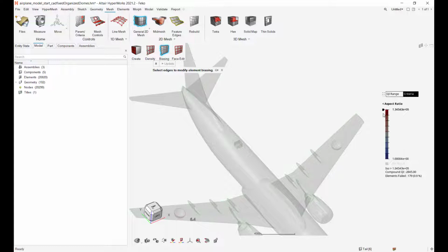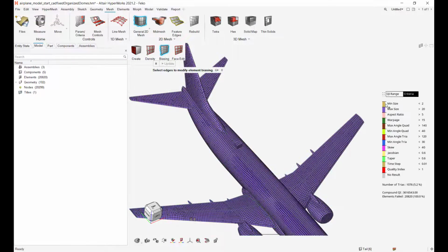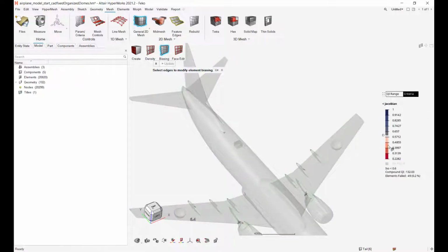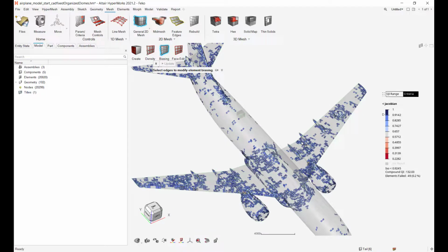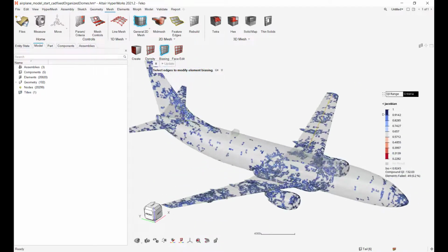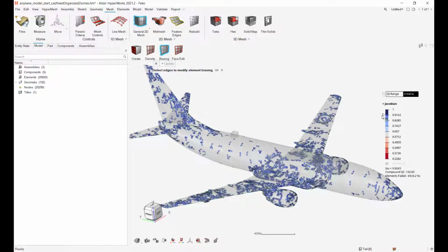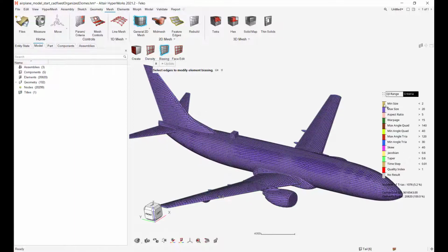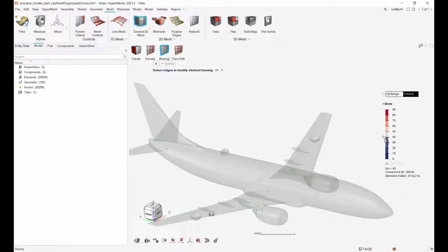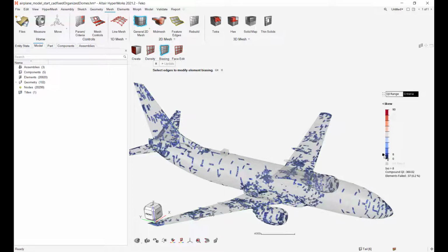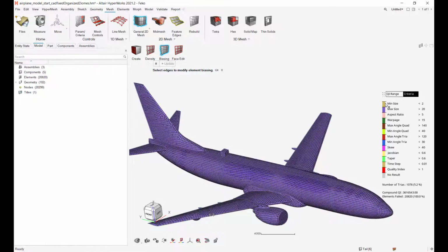As far as mesh goes, I'm not 100% certain what the most important thing is for, say, a FEKO mesh, but Jacobian is always a good overall measure of quality, right? So if you are just wondering about the quality of the mesh, okay, that's in there. Maybe taper or skew; those could be important, I suppose. I don't know how many of these. Yeah, the skew's pretty low on these, so. Just different options in here, right? So that's something that we can do.